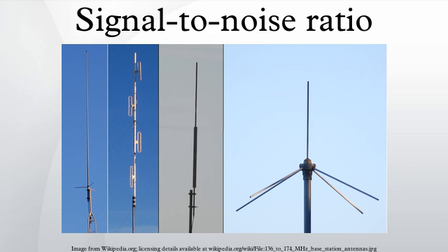This bandwidth is independent of the modulation format, the frequency and the receiver. For instance, an OSNR of 20 decibels per 0.1 nm could be given, even if the signal of 40-Gbit DPSK would not fit in this bandwidth. OSNR is measured with an optical spectrum analyzer.